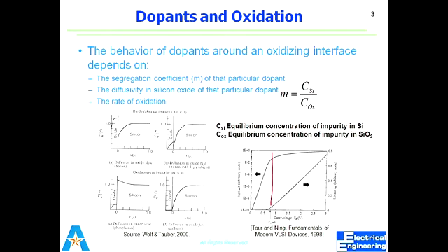But yes, the dopant is one of the causes that can affect it, in addition to several other parameters. The basic Deal-Grove equation takes into account only 3 basic parameters: temperature, diffusion, and reaction rate. You have seen F1, F2 and F3, the 3 fluxes. But yes, the dopant plays an important role, especially in the case of polysilicon. Even in crystalline silicon, a higher or lower dopant rate will affect the oxidation rate.